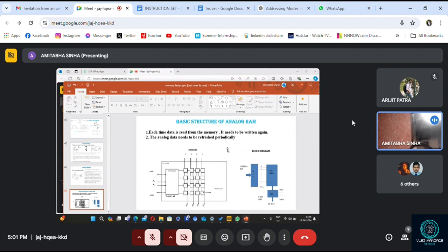For example, when data is transferred in a digital register from one register to another, say move A, B in the Intel format, it means transfer the data from register B to register A. Whatever was in B is not lost. Say an 8-bit register B has F2, and we execute the instruction move A, B. Then A will become F2, but the contents of B will not be lost.